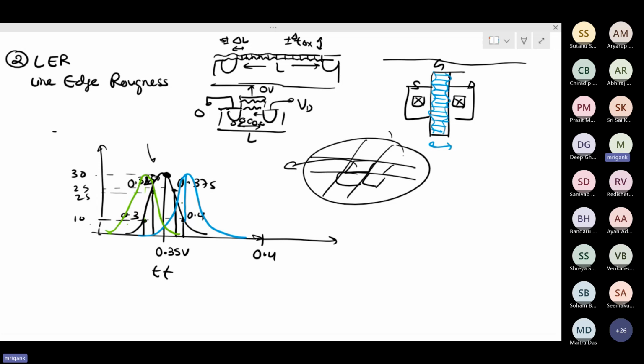So these concepts are very important in any practical circuit design. You need to be aware of both these process corners as well as random variations. Especially in analog circuits, it is much more important because whatever amplifiers, circuits, filters, differential units we are building, it assumes perfectly matched devices. And then in the actual circuit, we have this kind of variation. So both the process as well as the random mismatch need to be taken into account while designing practical circuits.